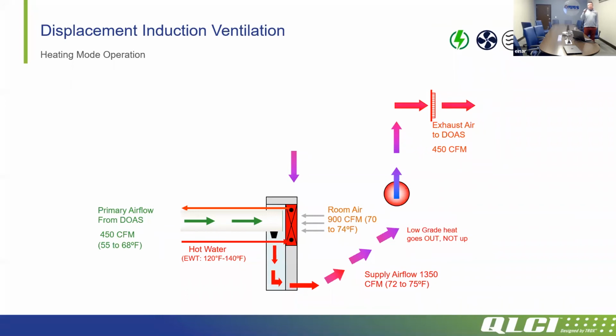I'm in Minnesota and you guys are in Colorado. And so when these are lined up underneath the window, we're going to have a cold draft drop. So this adds to the thermal comfort because that cold draft doesn't go out into the room. It actually gets sucked in and gets preheated or reheated before it goes out into the space.